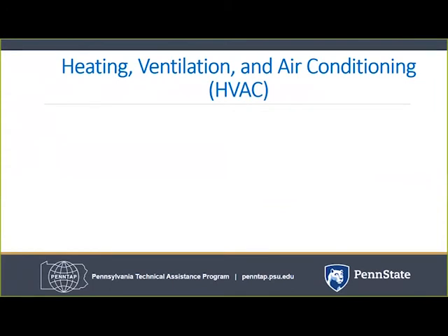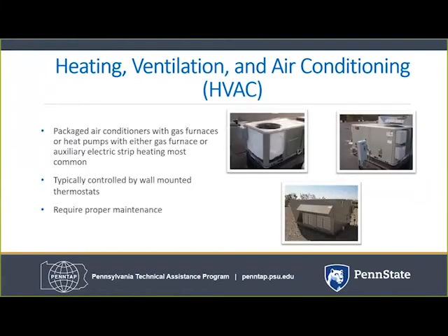In the next few slides, we will discuss energy-saving opportunities related to HVAC systems. The most common HVAC units are packaged air conditioners with gas furnaces or heat pumps with either a gas furnace or auxiliary electric strip heating. They are typically controlled by wall-mounted thermostats. These systems require proper maintenance to perform efficiently.